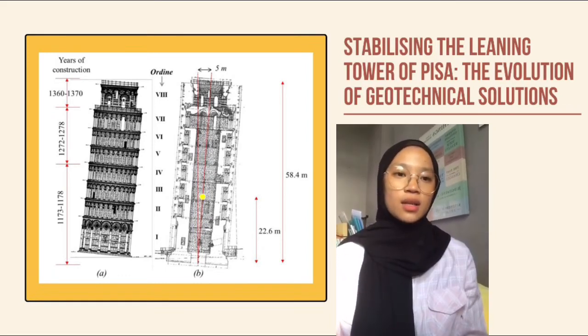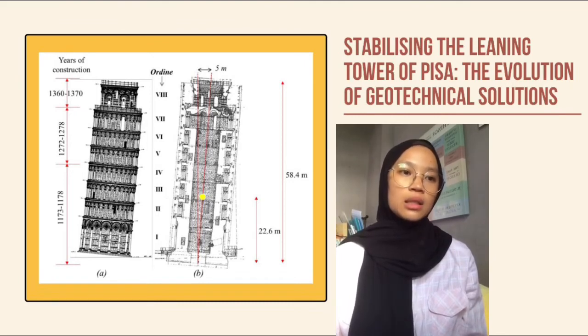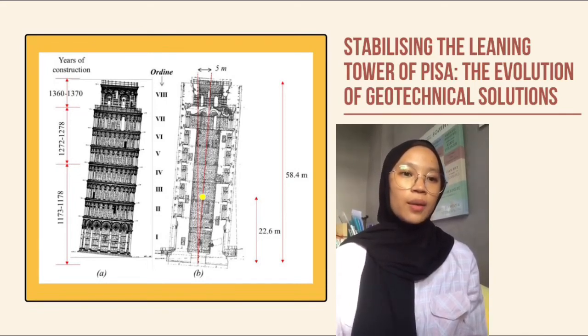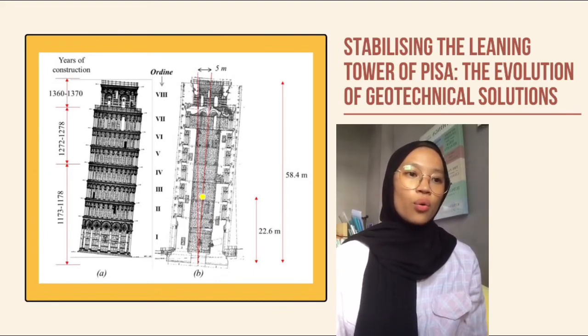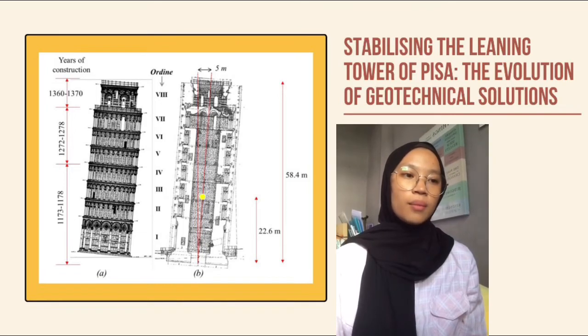Next is causes. Many soil borings around and even beneath the tower show that the surface of the layer is dish-shaped due to the weight of the tower above it. From this, it can be deduced that the average settlement of the tower was at least 3 m, a graphic demonstration of how very compressible the underlying soil is.